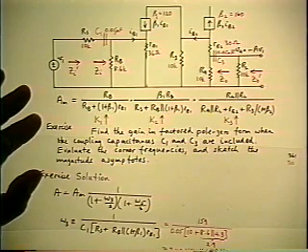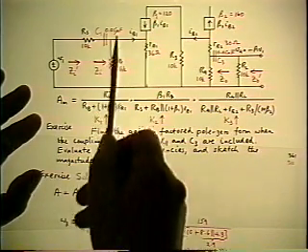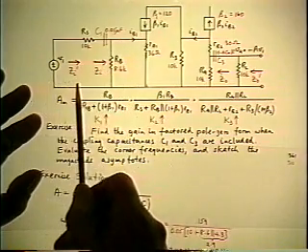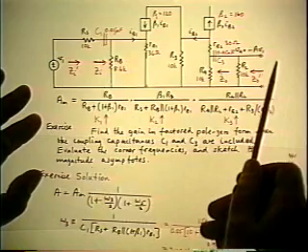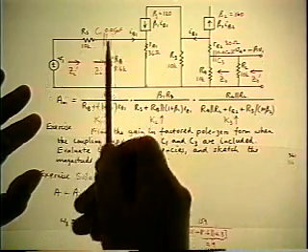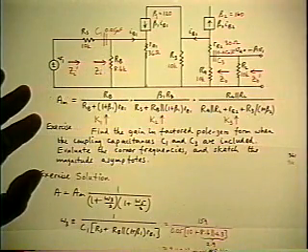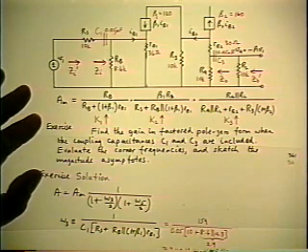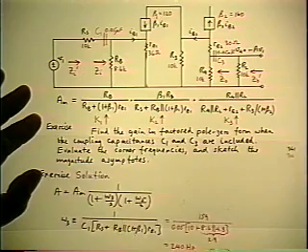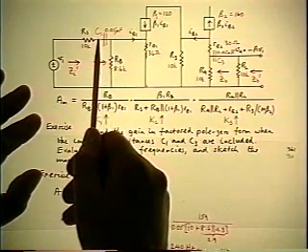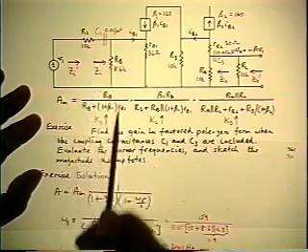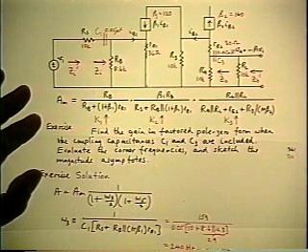As we already saw previously, this is an answer to be expected anyway, because the two sources are directly in series, and the only way you can get a null at the output is for the two sources to cancel each other directly, which means you have zero current everywhere. So you get an inverted pole as a result of the C1 and no inverted zero along with it.